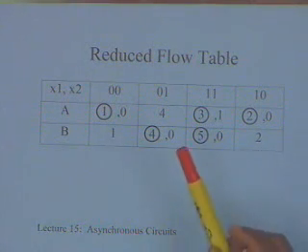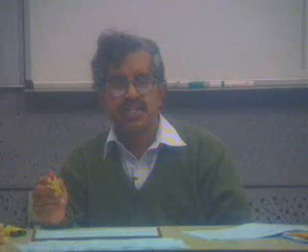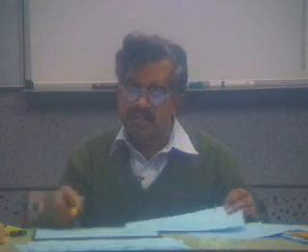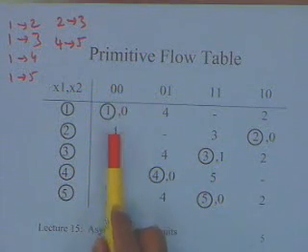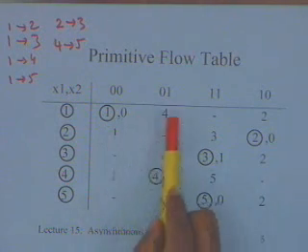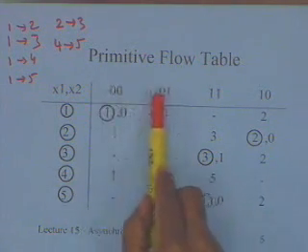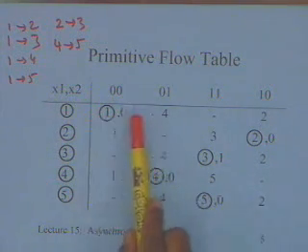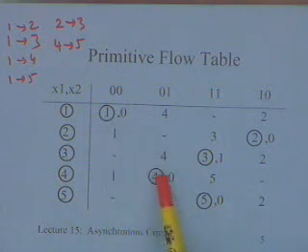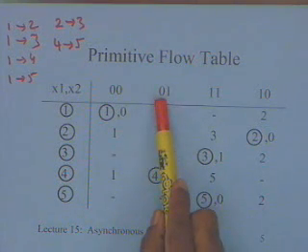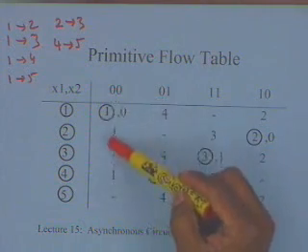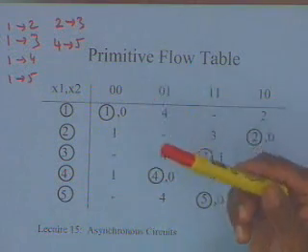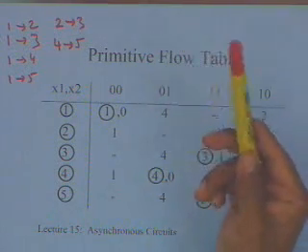The one question that may come is, why are we talking of only secondary states here? The reason is, when we are finding the compatibility, we only bothered among the columns, because an entry over here and an entry over here will anyway be differentiated by the inputs. So when I am talking of my total state, I do not have to bother about distinguishing between 1 and 4. 1 and 4 are going to be distinguished by the inputs. That is why compatibility I only have to consider in the column, and that is the reason after doing my merger graph I get the states which need to be distinguished by only the secondary variables.